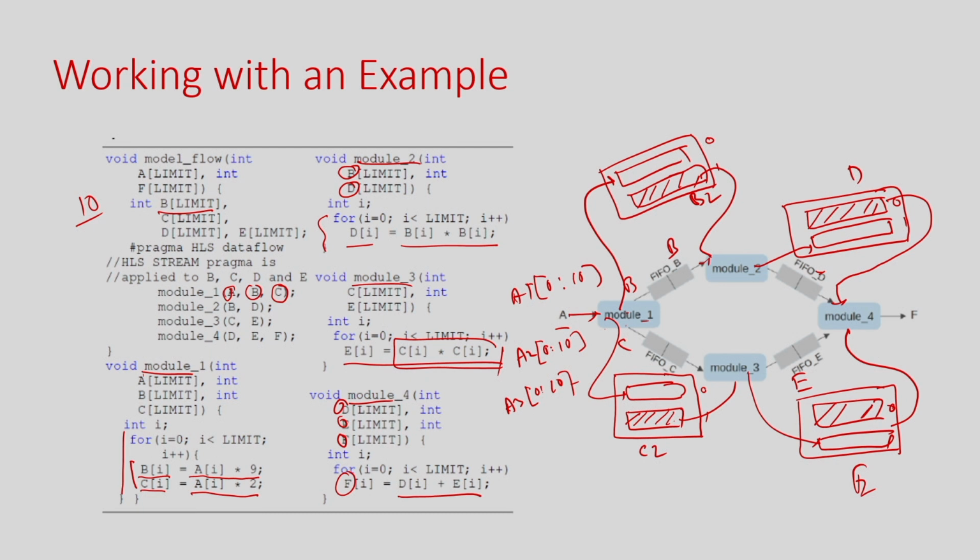The only thing is that if module 1 is slower, because it is doing two operations while the other is doing only one, then module 2 might complete the processing of the odd data earlier, and it has to wait, because the even channel is not full yet. Until that gets full, it cannot start the next iteration. That is where the synchronization happens, but in ping-pong style.